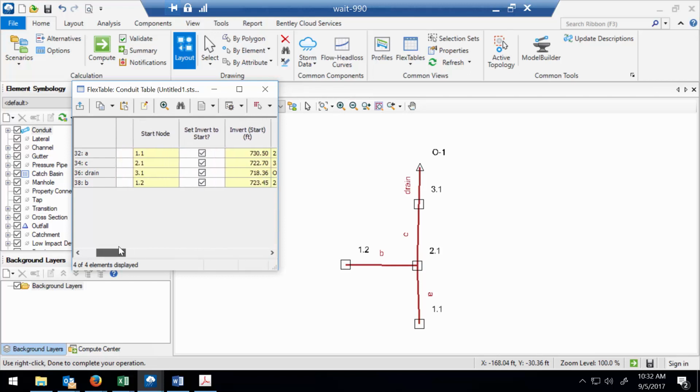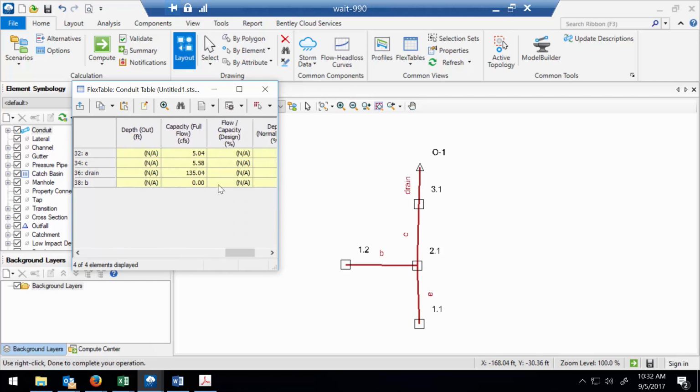All right, so we've defined basically everything we need so far. What's interesting is you'll see it's already doing Manning's equation. It's solving, if the pipe was full, what would the capacity be for that pipe? But what it hasn't calculated yet is the ratio of the actual flow rate during peak conditions to the capacity. This percentage is going to be a really useful way for us to know if the pipe is oversized or undersized. So far, it's not defined because it hasn't actually calculated the rational method. It has calculated Manning's equation already, and that's the result of this.